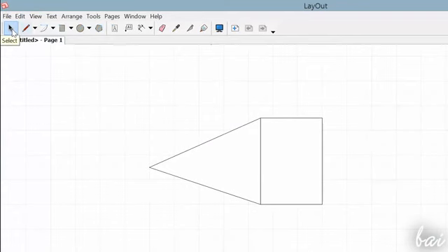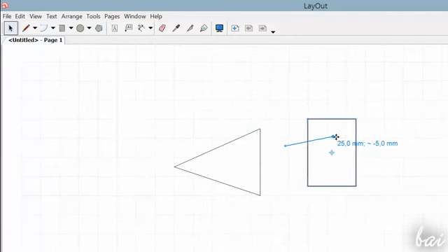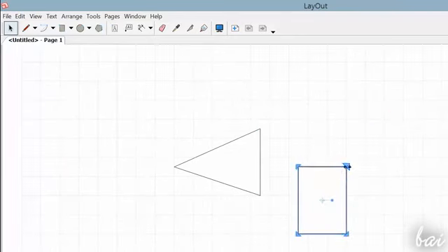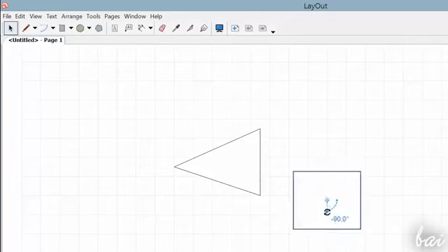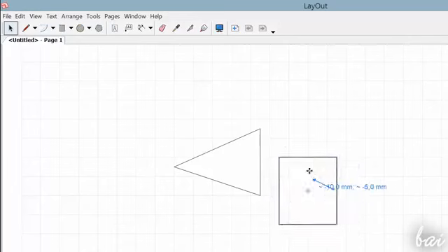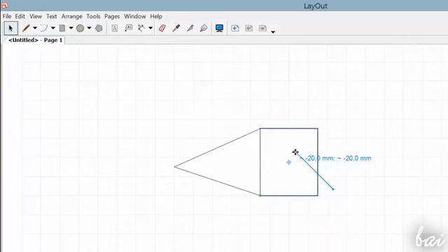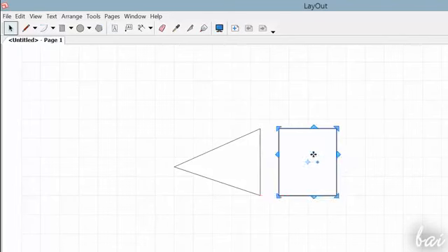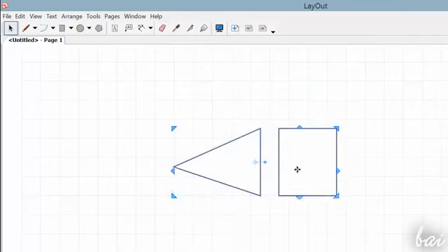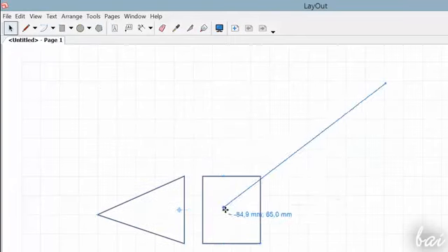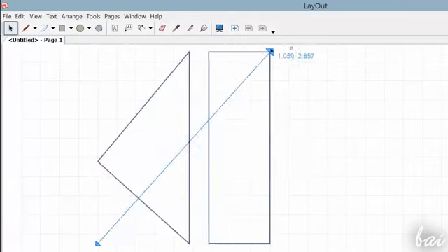You can edit each object easily with the Select tool enabled. You can click and drag to move. Drag from the blue arrows to scale. If you hover the small blue node on the center and then click, you rotate the object. You can also edit more objects at the same time. With the Select tool enabled, click and drag and include in your selection area all objects interested. In this way, any editing applied will affect all objects inside.